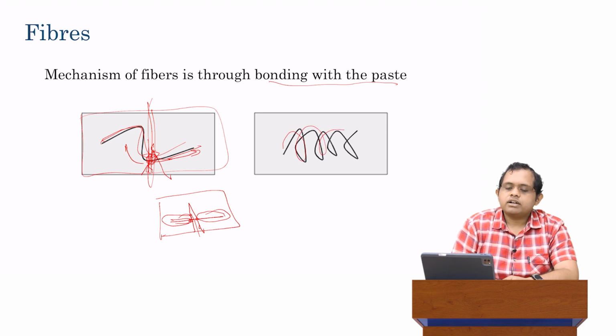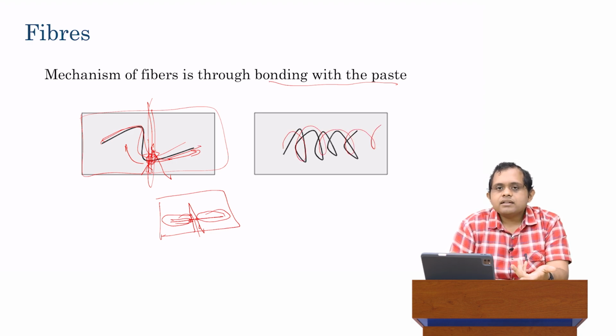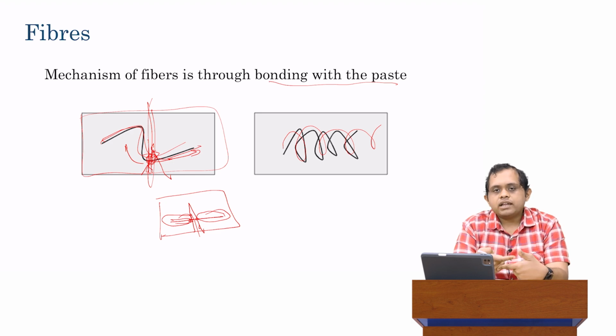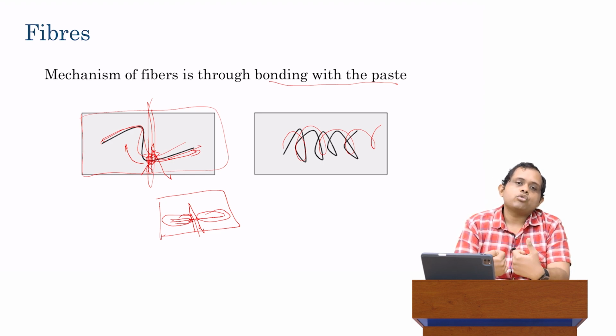And so the two figures I have over here, this is when you have a relatively short length, this is when you can have a relatively long length. Both could be the same fiber, the same material, the same cement paste, but the second one, because it's much longer, will have simply more area or more length of bonding, and because of that, it's going to require greater force or greater stress in order to cause any pull apart or breakdown of that bonding.